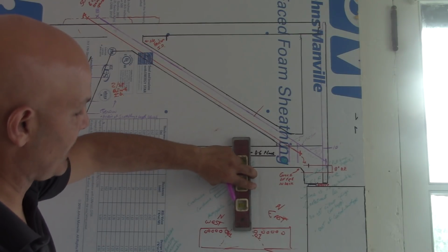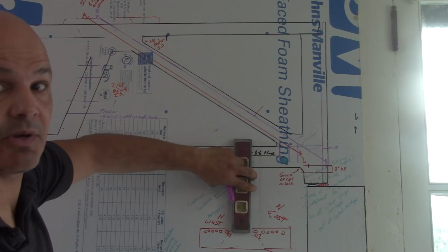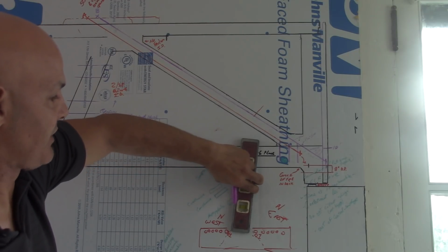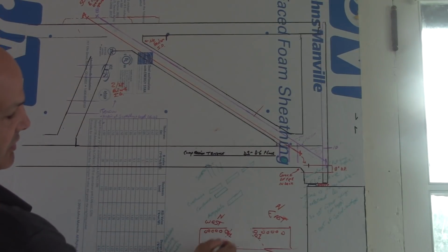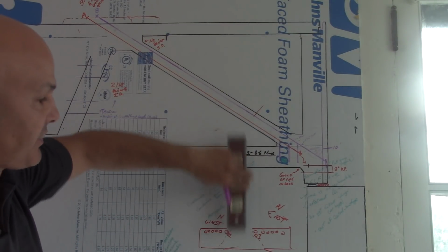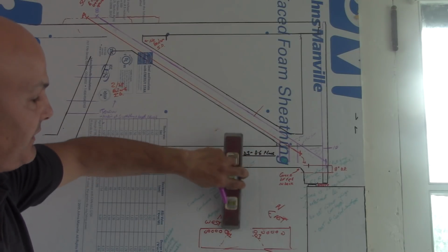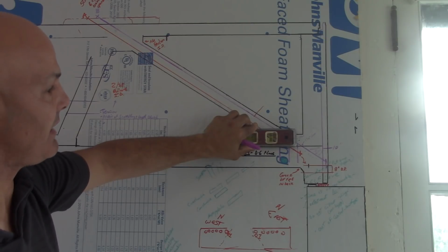This is after post-tensioning release. It no longer had the clamp force. This is over many days, creep also. So it did a rotation like that column. But this is what shear looks like. Now, if that's what shear looks like from this position, you guys can clearly understand the failure there, especially looking at the other video. We just turn the direction of the shear path, right?